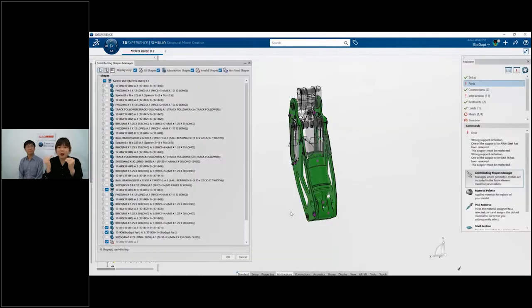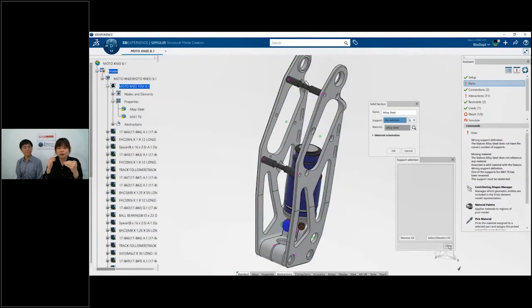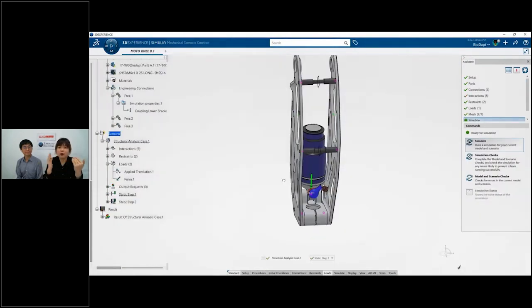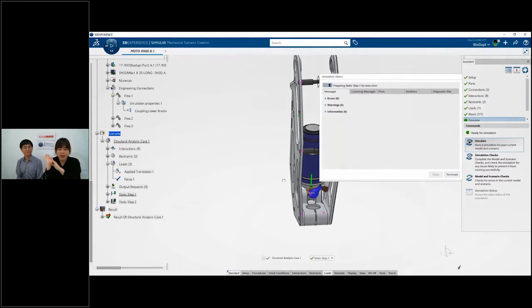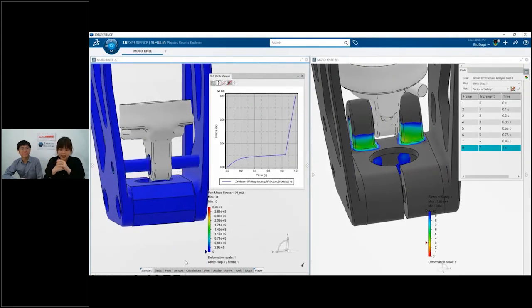He will now need to compare the redesigned model with the previous ones. So instead of needing to rematch the assembly files or apply a new mesh, he can skip everything here. All he needs to do is just open up the original design and replace the old model with the redesigned model, then proceed to rerun the study. That's it. So with the results completed, he will compare the two studies, so he can read the strength of the new brackets and compare them side by side.